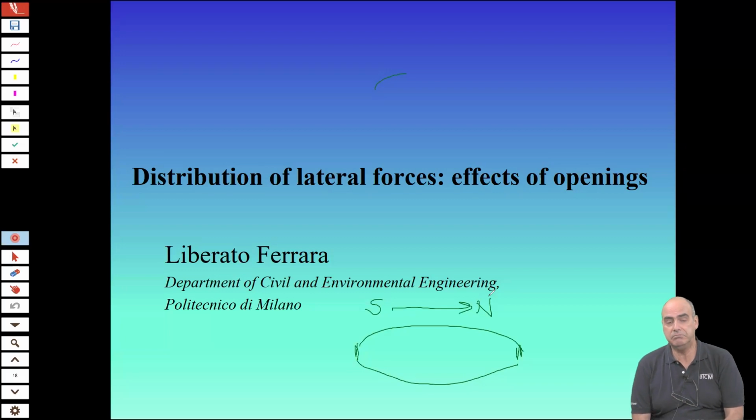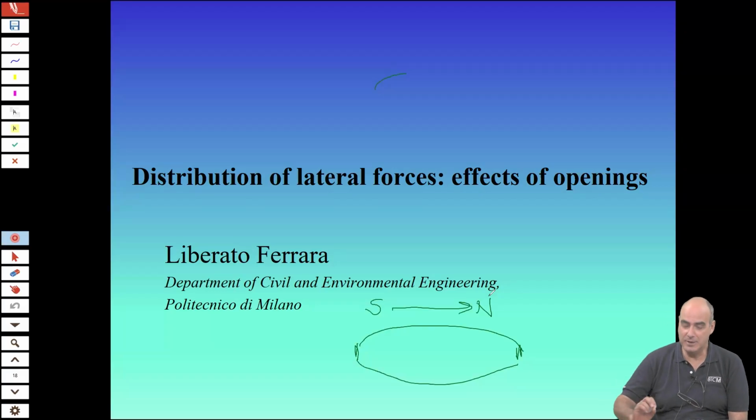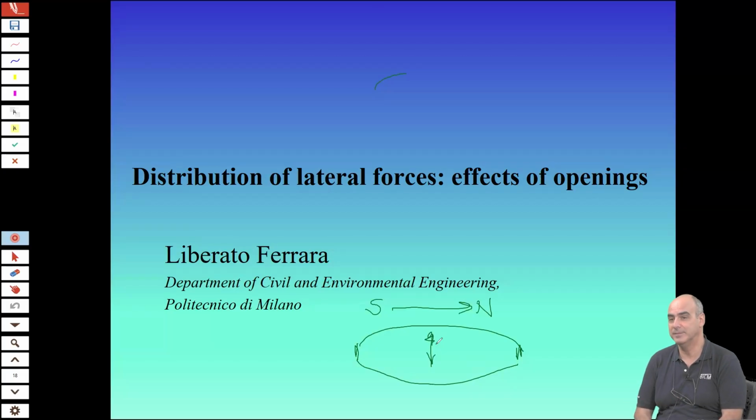Well, not more than 10 years after the construction of the building, the family abandoned it. The issue was the vibration in this direction. Because you see, this building is very stiff in one direction, which is the direction of the main winds, but it's not much stiff in the other direction.